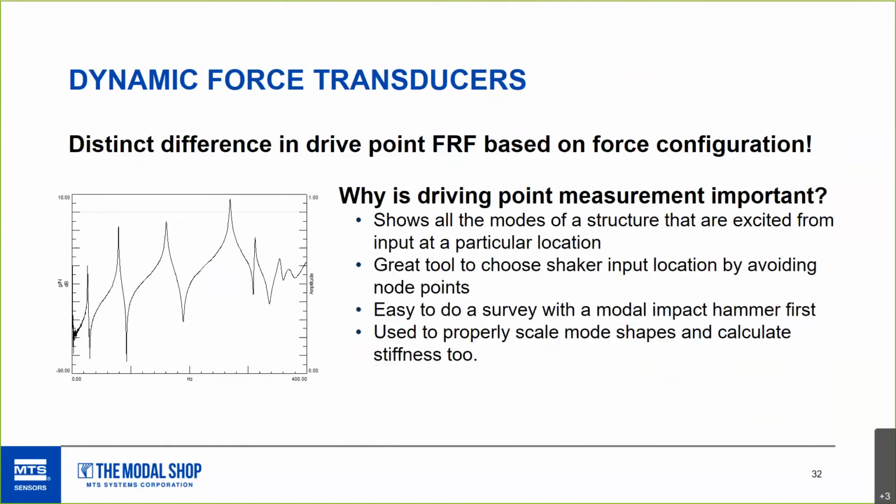Then, why do we mention this, or why do we care about that driving point measurement? The driving point measurement is another great tool that you can use when setting up your modal test to help alert you if you have a good position for your hammer or shaker. A driving point is going to show you all the modes of a structure that are excited from that particular input location.